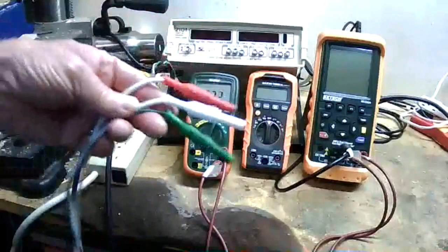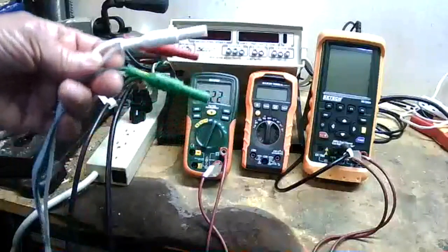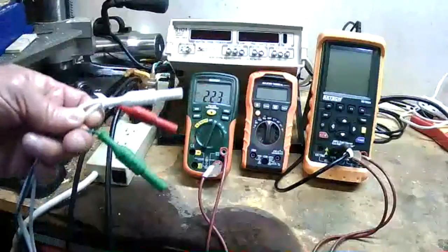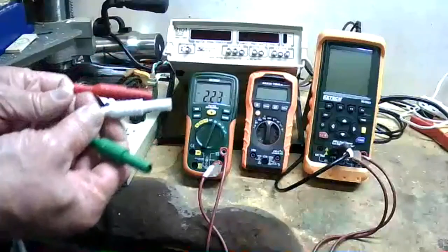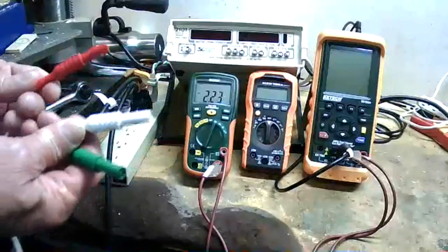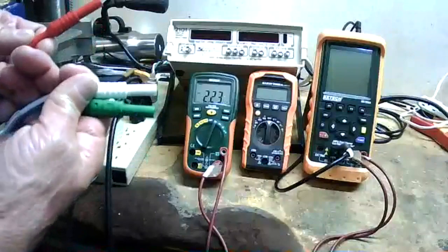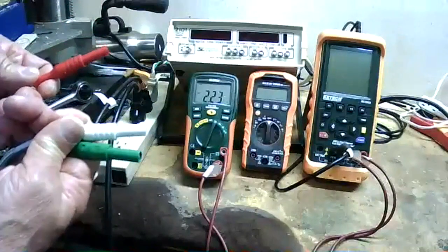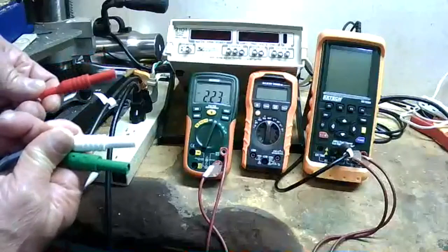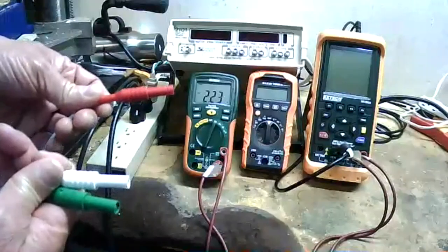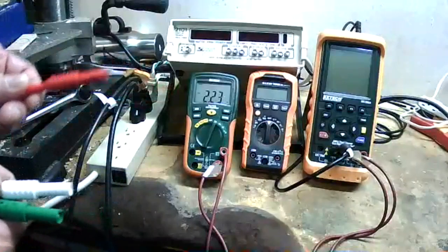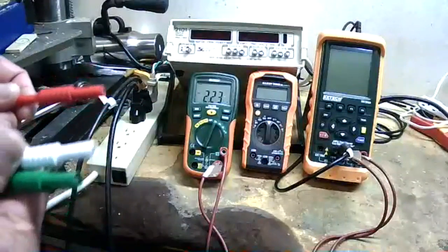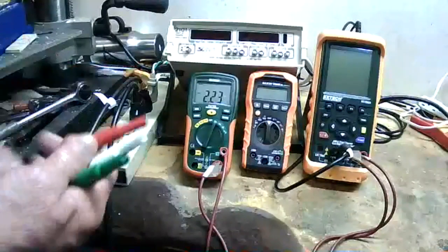I also checked the wiring on these leads. The green is the safety ground. We'll be talking more about that. The white is the neutral. These two are both connected to ground at the service entrance for our house. The red one is the energized conductor. That's the one that will be 120 volts above neutral and above earth ground.